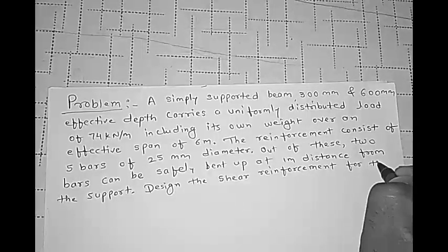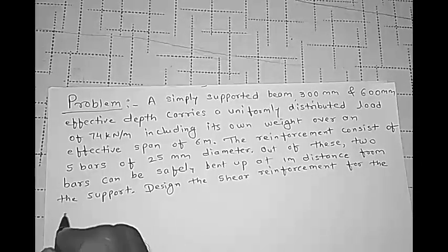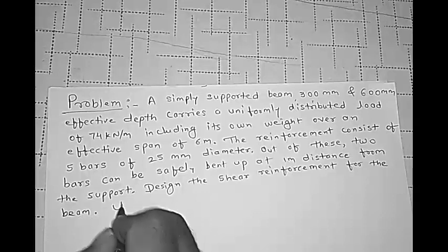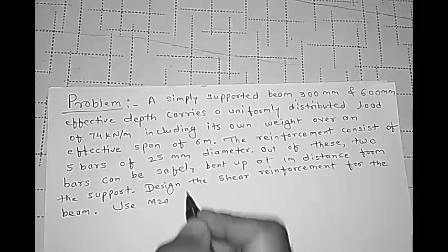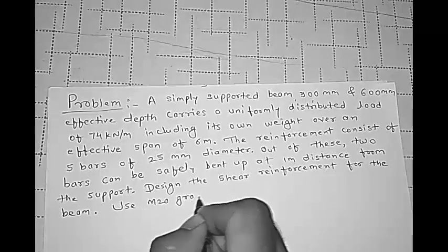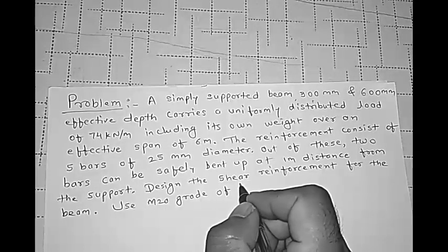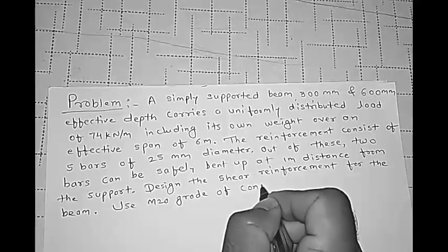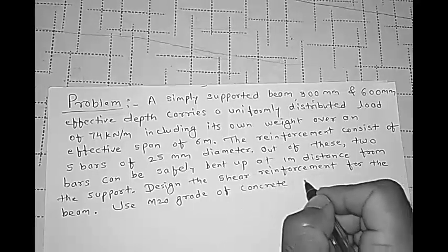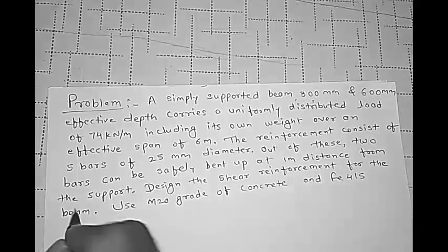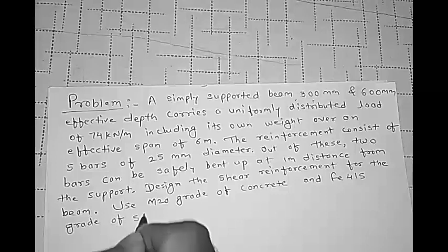For the beam, use M20 grade of concrete and Fe415 grade of steel.